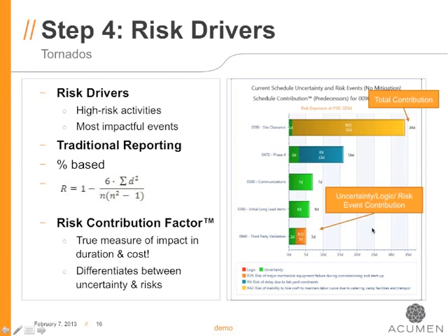So there's an example of this on the right-hand side here. Our P50 date, you can see, has a risk exposure of 103 days. In other words, we are 50% certain we're going to be 103 days later than planned. That 103 days is driven by 34 days because of site clearance, 16 days because of phase 4, and so forth. Now, taking that a step further, we've even now established a means of saying, okay, well, site clearance is causing a 34-day risk exposure.